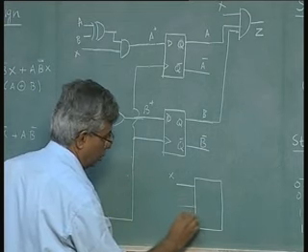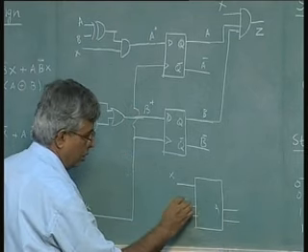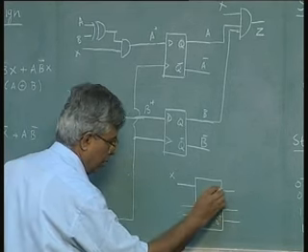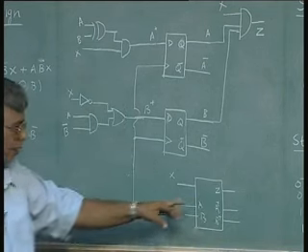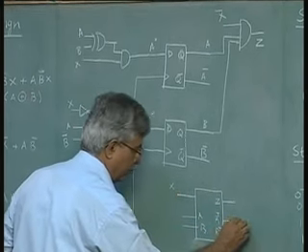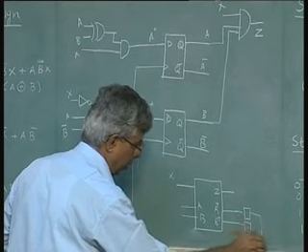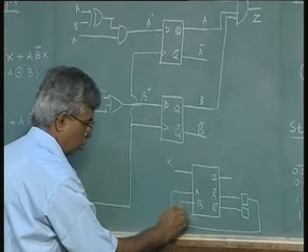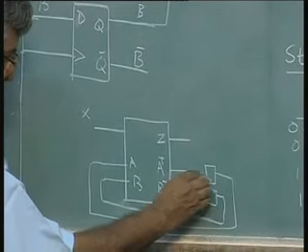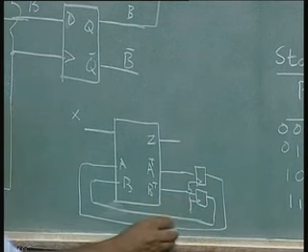So, we combine x, A, B to get A plus, B plus and Z. This is a typical Mealy circuit because the output combines the present state variables and the present input, and the next state variables are obtained here using flip flops, which are fed back, with the clock shown here.